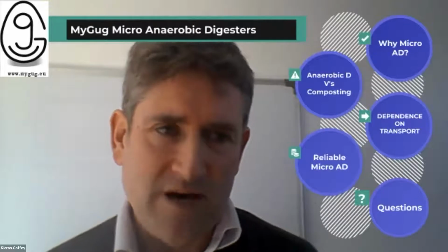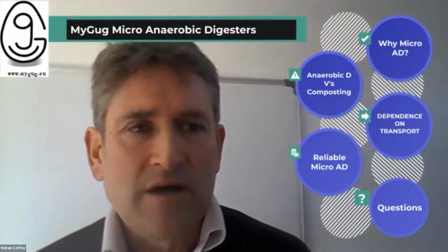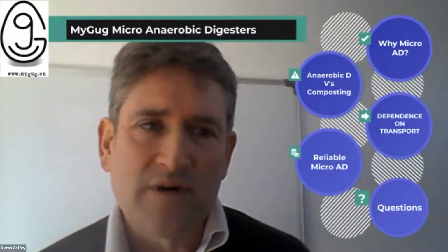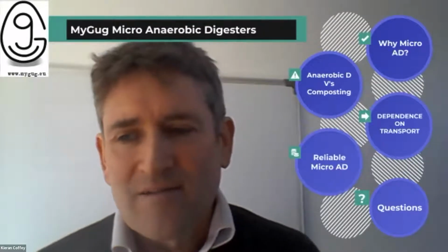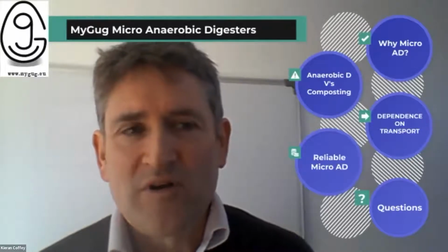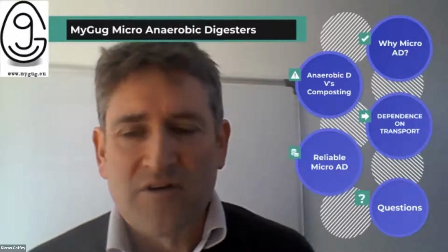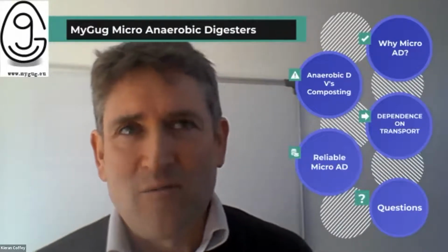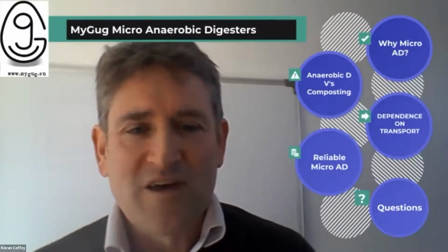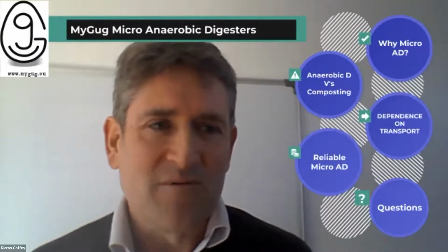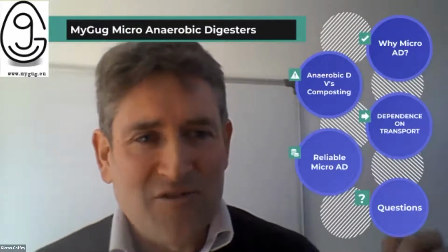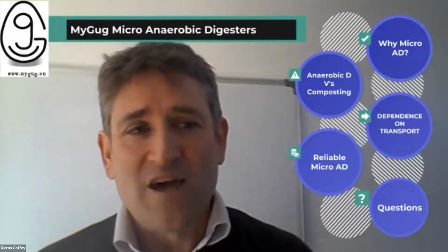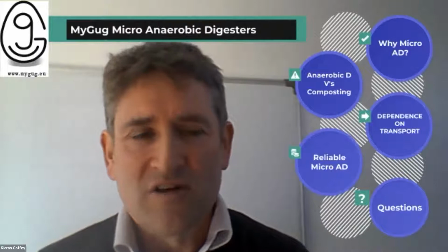And again, like I said earlier, liquid wastes will come into this as well. So if you have yogurt or milks or juices or anything with sugar in it, that can all go in as well. I'd like to highlight that generally that's not considered a food waste, but anybody who gets rid of waste milk or milk that's gone off will pour it down the drain. And that then ends up in a wastewater treatment plant, and a litre of milk has a biological oxygen demand of about 30,000 milligrams per litre, whereas a litre of sewage has a BOD of 220 milligrams per litre. So it puts a massive strain, and there's a cost on the wastewater treatment plant when liquid wastes go down a drain, whereas in our system you're harnessing the energy in it and you're using it, and also you're harnessing the nutrients.